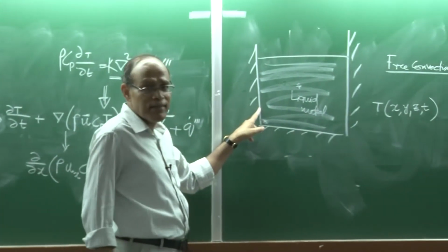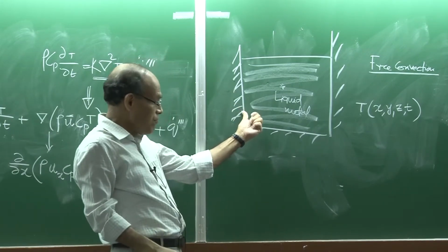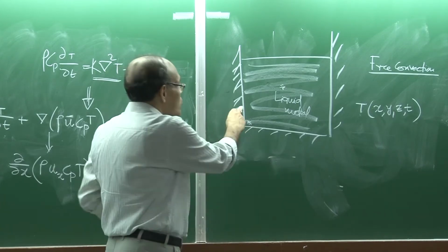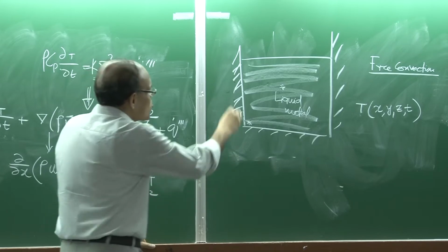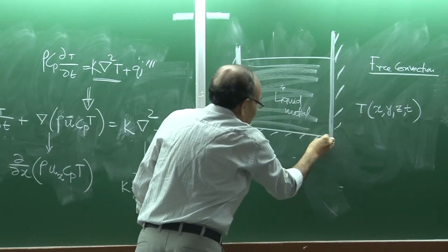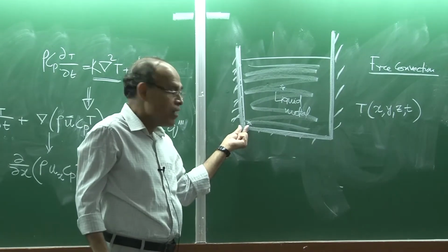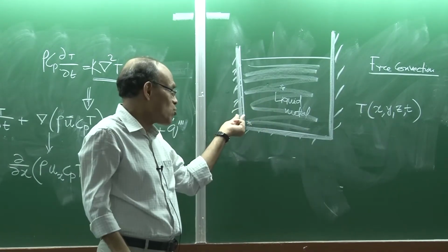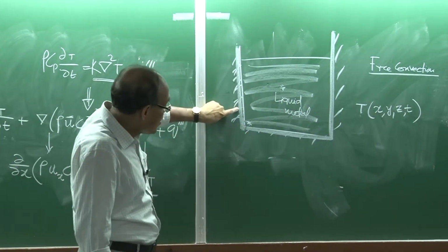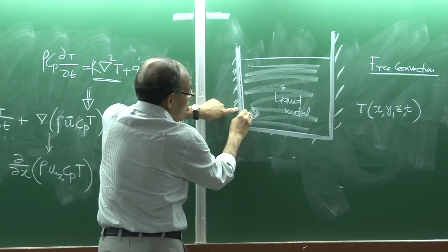But the boundaries here are going to be the same; we have a heat flux here, for example. Or if the temperature is remaining constant at the surface, I can apply a constant surface temperature here. But it is not so straightforward a problem, because we get to complexities, because there is a solid here. So, this is actually a conjugate domain: we have solid here and then the bulk is liquid. So, it is a sandwich domain, a conjugate problem. At the surface here, convection-diffusion is present, but only conduction, or diffusion, is present within the solid.